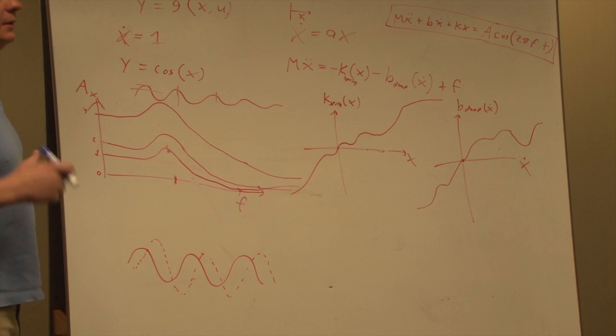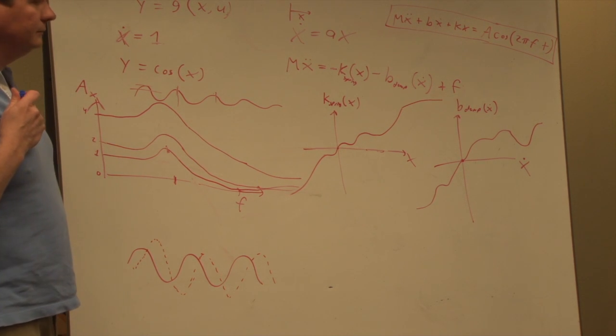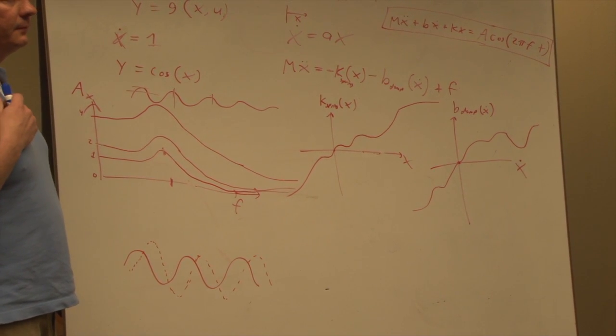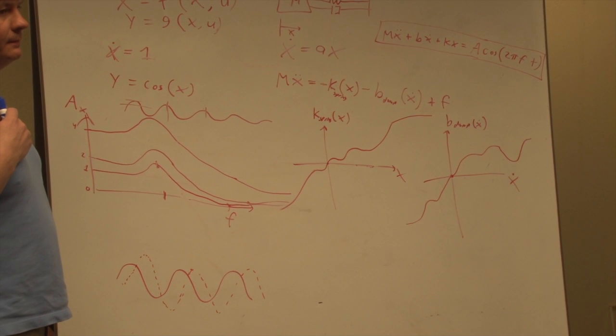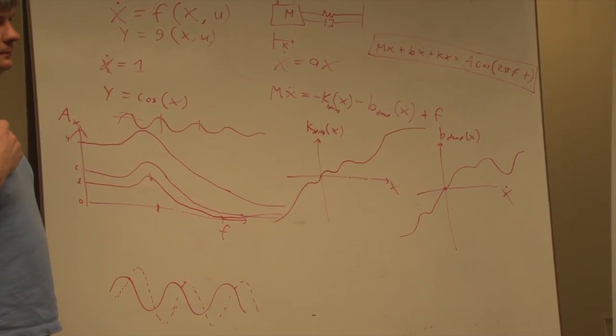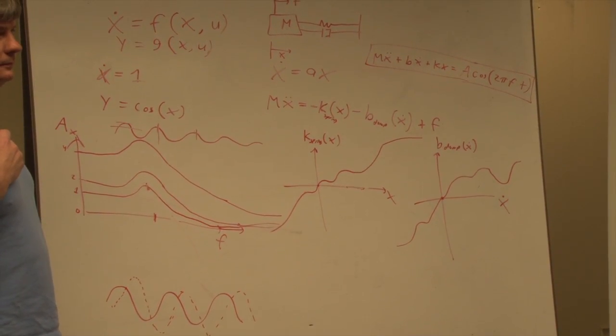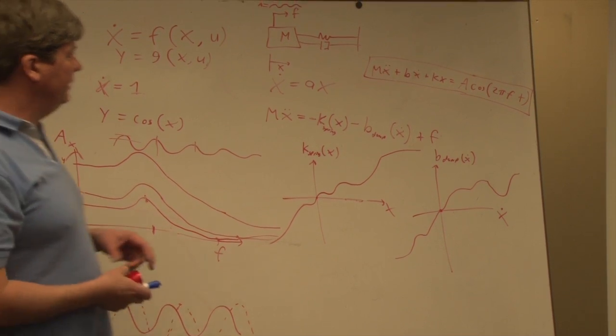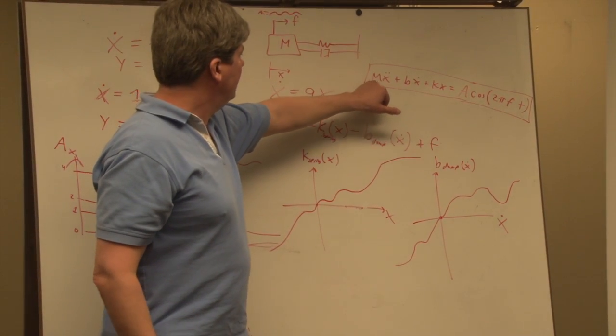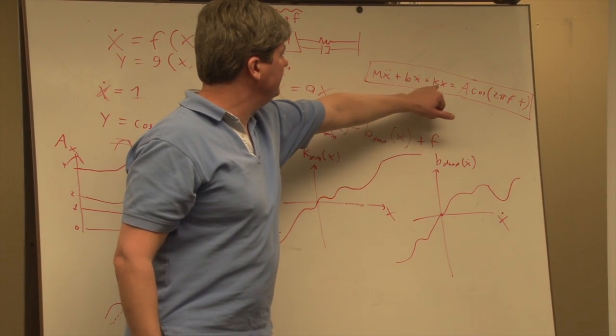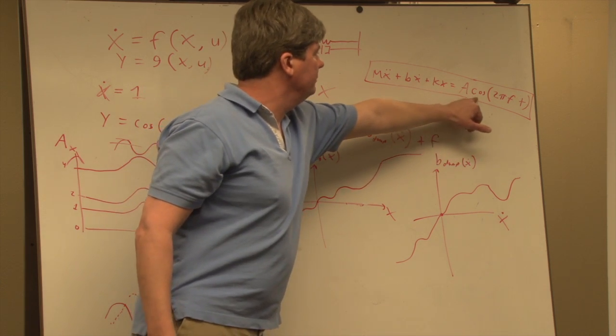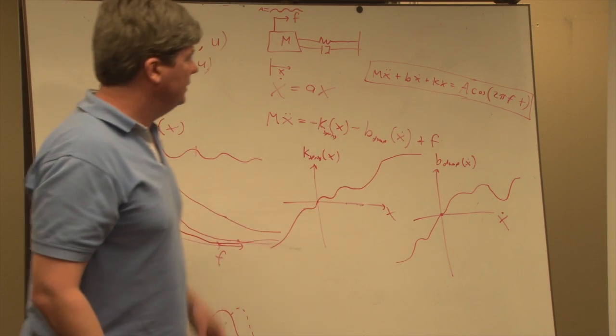All right, makes sense? So there's multiple uses for linear here. A linear system gives you the scale the input, you scale the output, but this is also assuming a linear spring, because you get weirdness when you start. Right, by linear it means everything's linear. The constant mass, constant damping, constant spring, and the input is just a cosine or sine.